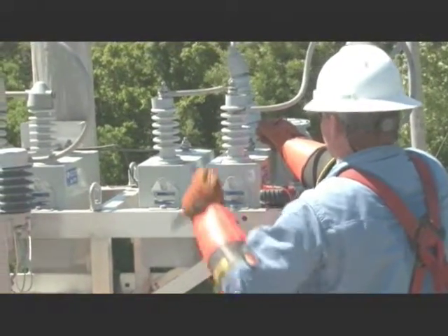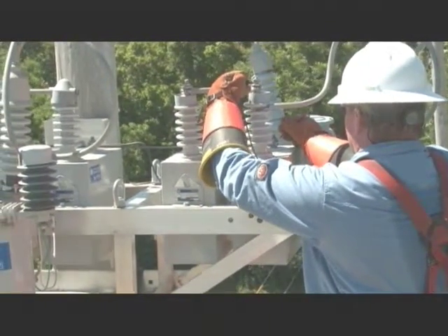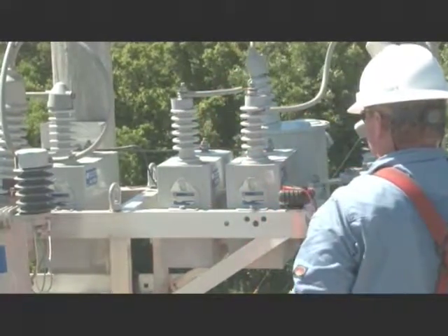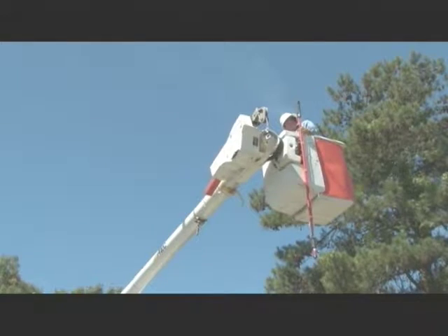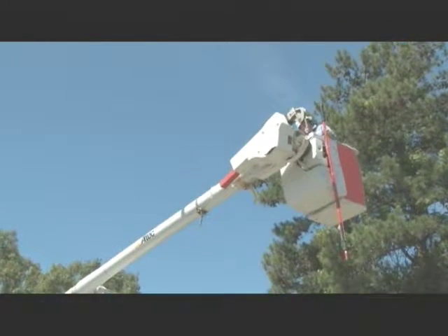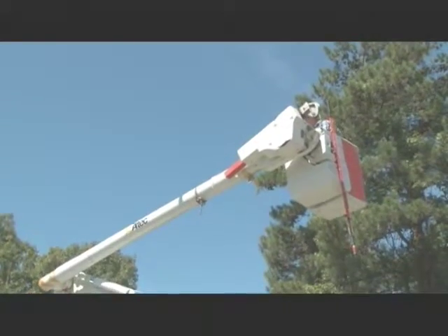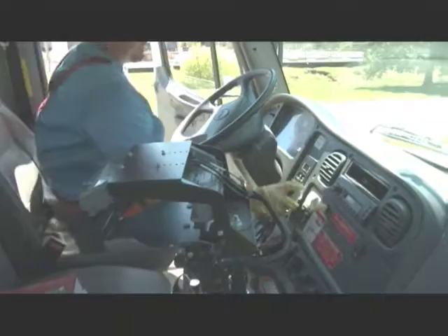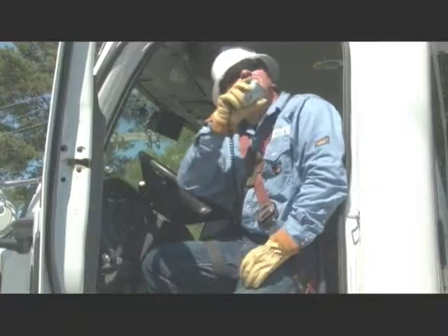If there are no visual signs of damage, the lineman then uses a C meter or capacitance meter to check each capacitor. After comparing the C meter reading to a range chart, one capacitor was found to have been damaged. The line worker leaves the capacitor bank disconnected for the changeout crew. The line worker notifies the proper authorities that the capacitor bank has been damaged and is inoperable.